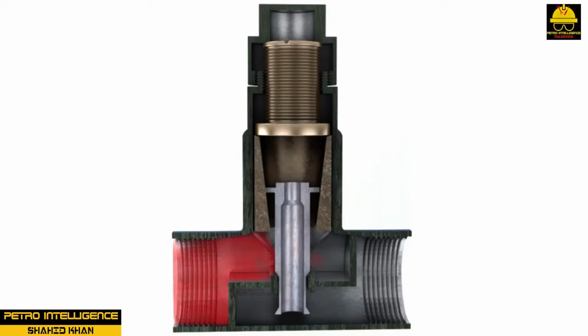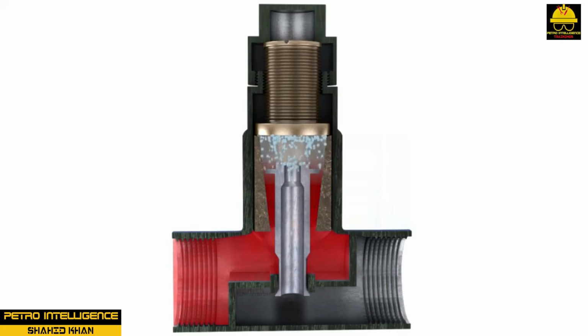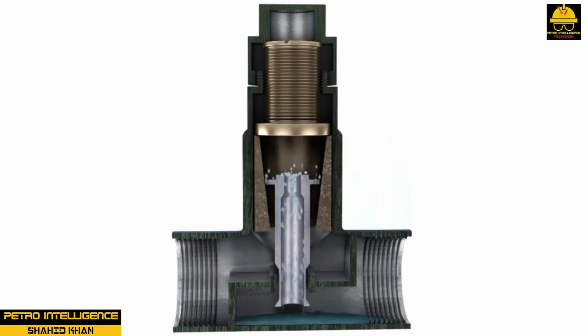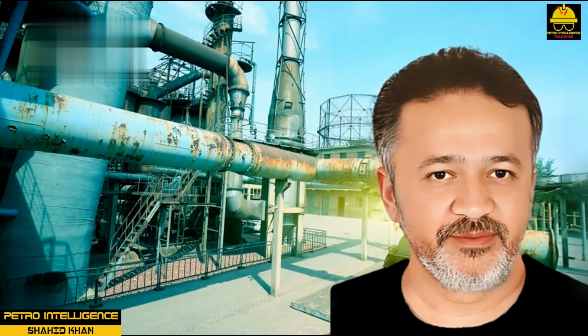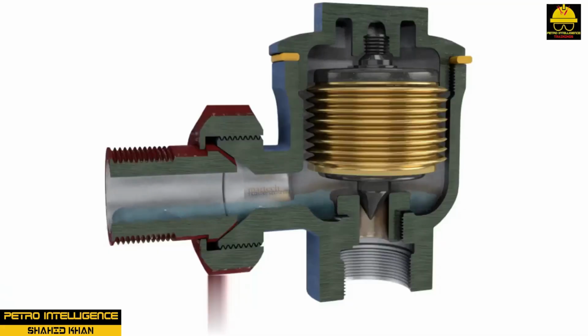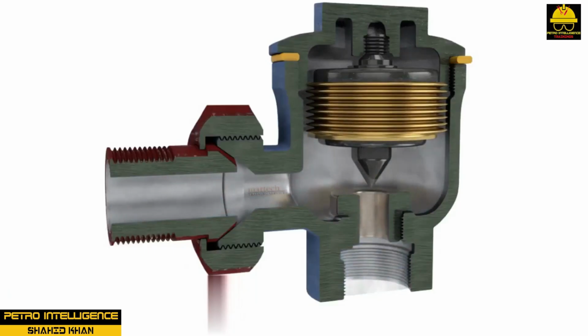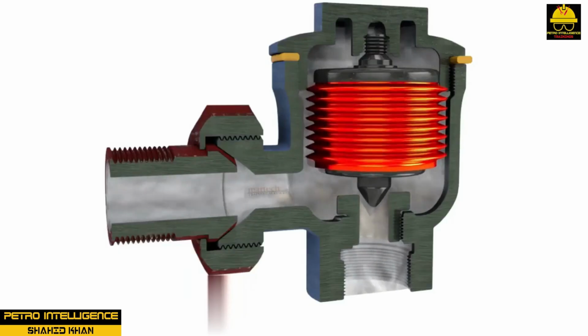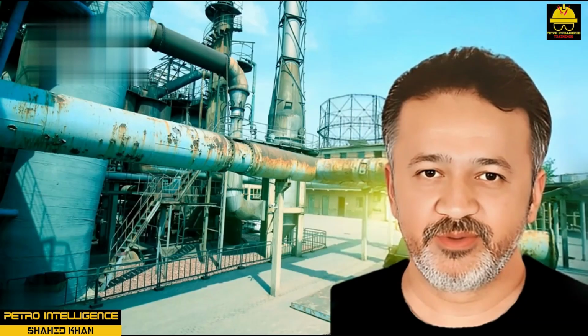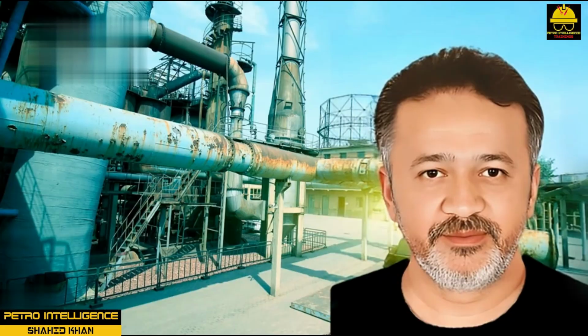Impulse traps are used on steam tracers and drip legs. They do not operate at pressures above 300 psig or below 15 psig. Impulse traps will fail to open. They are self-draining when installed in the vertical or horizontal position with the cap on the side. Thermostatic bellows traps are used in intermittent and 5 psig or lower service. An 18-inch minimum vertical leg is required for horizontal or vertical installation. Bellows traps are self-draining when the outlet is vertical.